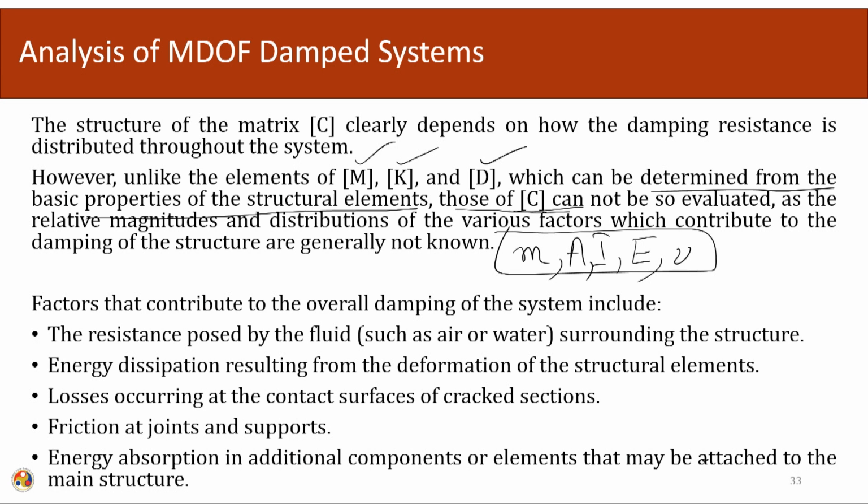It is not the actual damping in the system, we are representing it by a viscous damping coefficient. So, the direct calculation becomes cumbersome, tiresome, and this is not the proper justification, because what we are doing is representing the effect only. The cause might be due to some other mechanism, but we are representing just the effect by a viscous damper. This is in contrast to the mass and stiffness matrices, which are direct properties and can be directly calculated, but this damping property is not a direct property. So, we are using just a representation.